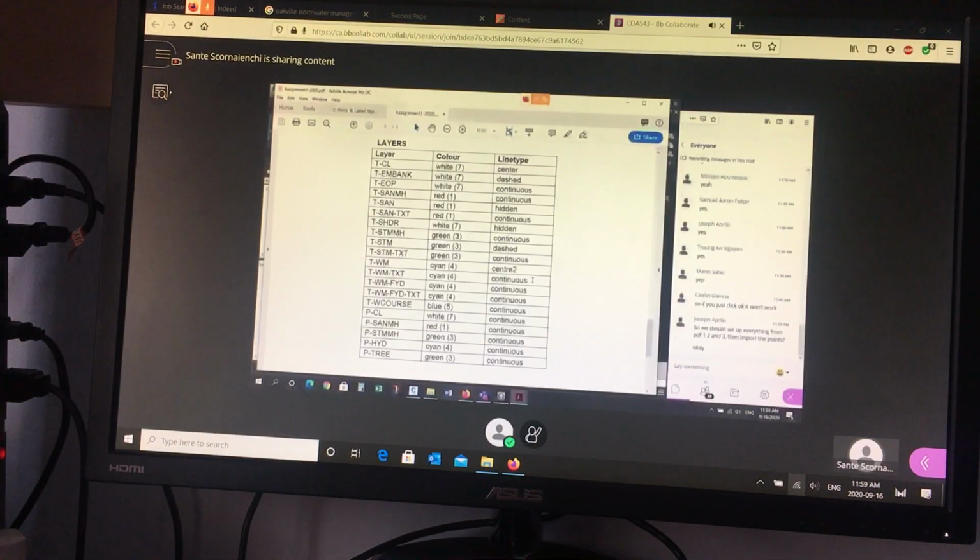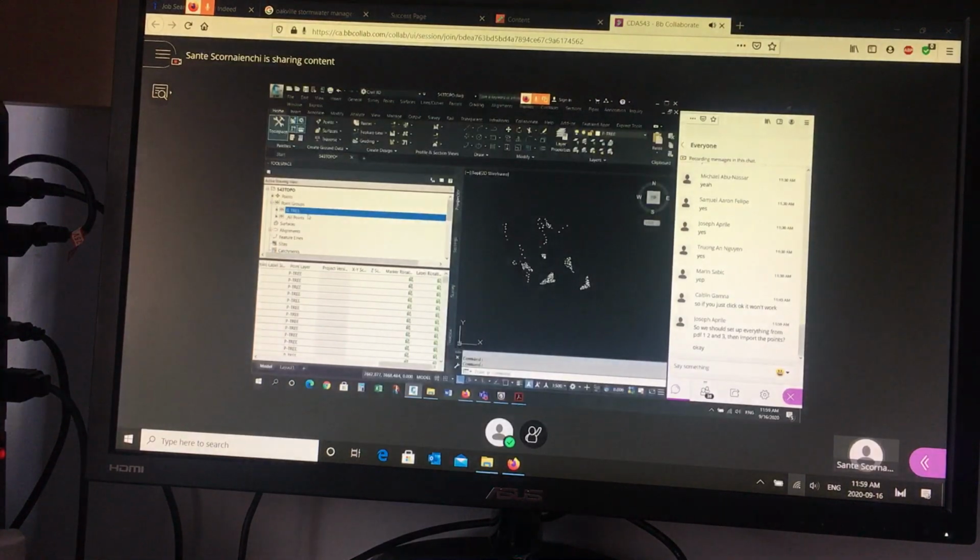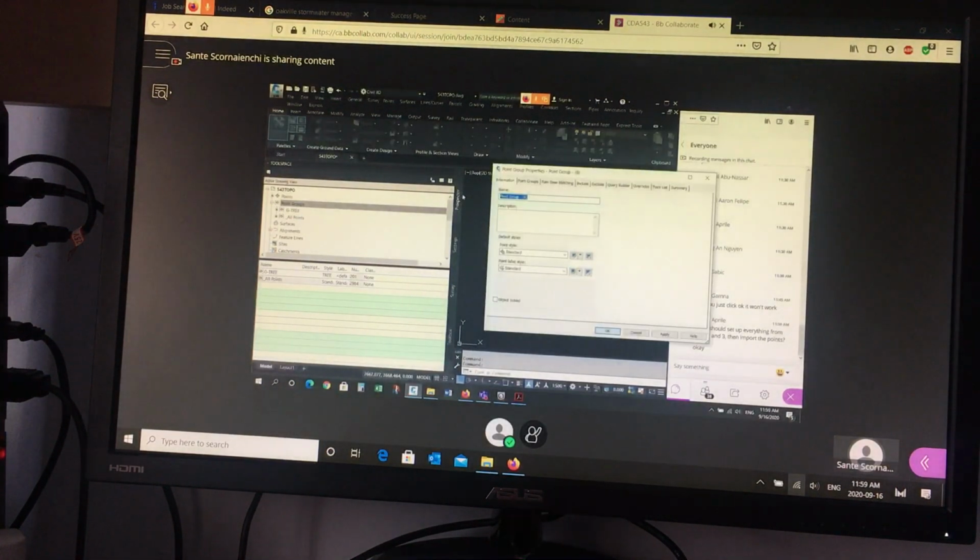Yeah, that's best practice. I mean, can you create the groups first? Yes. But when you go to create the groups, again, I'm just trying to be efficient. Cancel. I didn't create all my styles, remember? So if I go here and I right click and I say new, and I create one called G sanitary maintenance hole, one of the groups is G sanitary maintenance hole.